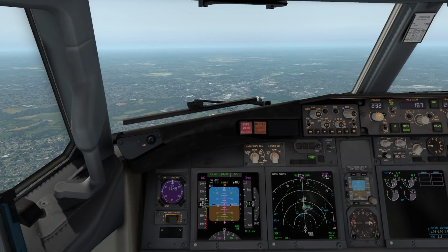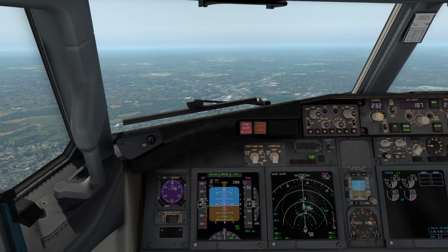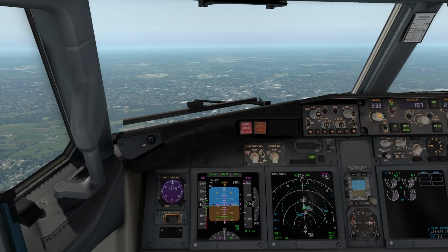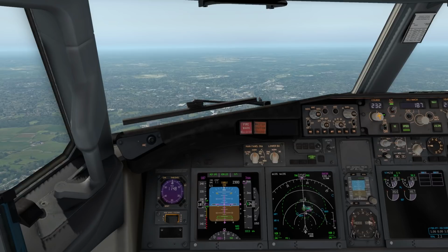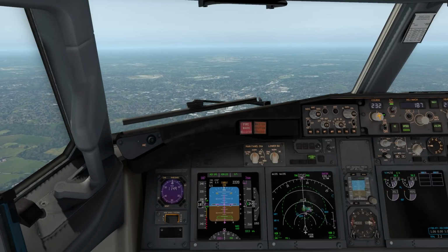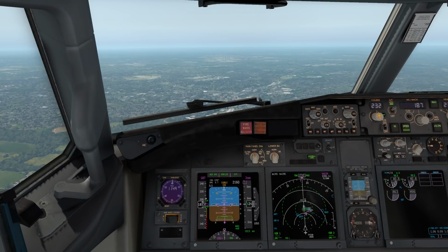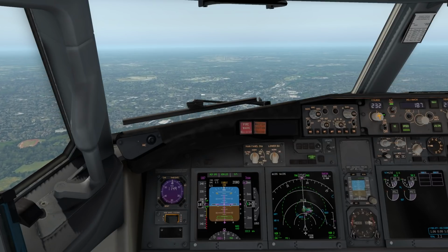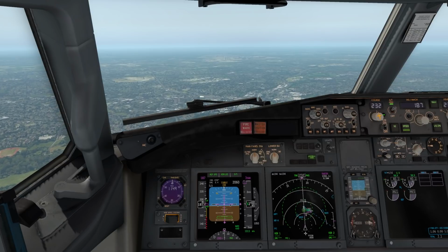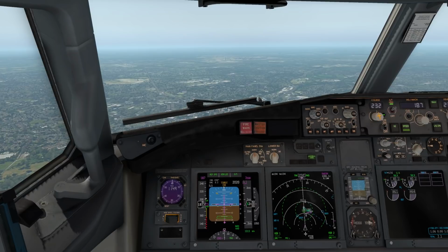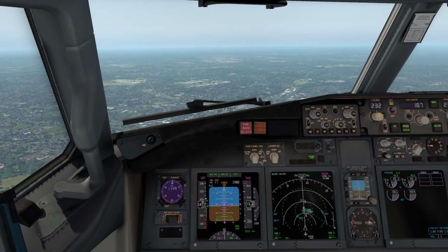One of the things that I would have highlighted, having just jumped into the passenger view there, where they could see the flaps are up, I'm sure most of you watching would probably notice that would be the case. So we would have done a reassurance PA to the passengers, just telling them that, we'd be honest, couldn't get the flaps extended here, but the approach would be a normal approach, flown a little bit faster than usual, and that after landing we might have the emergency services just inspecting the aircraft, and the landing would be quite firm as well. We would have, of course, briefed the cabin crew of this situation too.